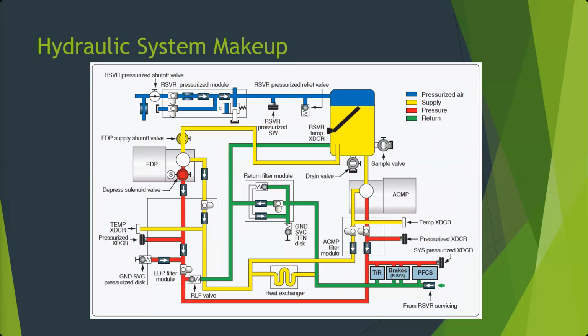Some of them are upwards of 60 amps. They're pretty high. They can draw a lot of current on big aircraft because they're converting a lot of power into hydraulic power to power things like landing gear. Some of the biggest loads on your airplane aren't your primary flight controls, but rather when you go to extend or, more importantly, retract the landing gear, that takes a lot of fluid. Flap systems usually are pretty hydraulic intensive if they're a hydraulic flap system. And systems will be different sizes too. Some systems may have a much larger reservoir, other systems may be smaller, depending on the capacity of all the items connected to it.